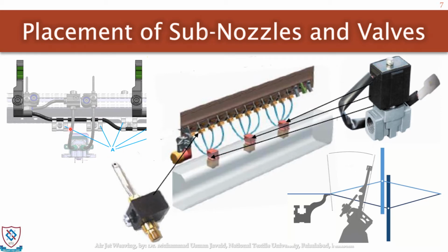That is why the air is consumed in high quantity, or wasted, or high-speed, high-rate weft insertion is not possible. All these can be prevented by placing the valves on the sley and shortening the length of these pipes, so a release of pressure is quickly possible.